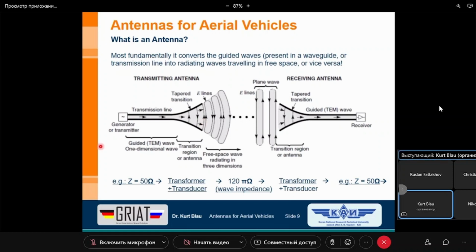Okay, but let's assume again 1 volt peak voltage, and then we have no information at this moment what power goes into the transmission line. So we have to know the input resistance or the input impedance, and not only the general input impedance. Impedance consists of a real part and imaginary part. We are interested in the real part. We want to know something about the power. Means we have to know the real part of this line impedance.